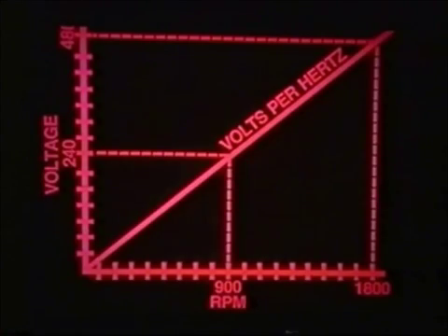The second type of automatic voltage regulator is designed to not only sense the alternator's terminal voltage, but also monitor its frequency, and will maintain the unit at the preset voltage only when it's operating at the rated frequency. If the rotative speed is either increased or decreased, this regulator will cause the output voltage to increase or decrease in proportion to change in speed.